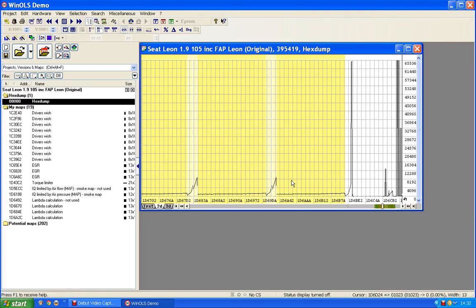Okay, for this video I'm going to have a look at what's known by most people as the torque to IQ or injection quantity conversion map. You don't find this in EDC16 maps because they're not torque based, or EDC15 files because they're not torque based. They are based on injection quantity all through, but the EDC16s are torque based, so you need a torque to IQ converter